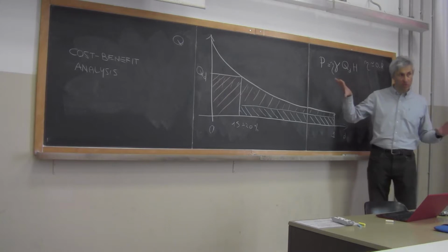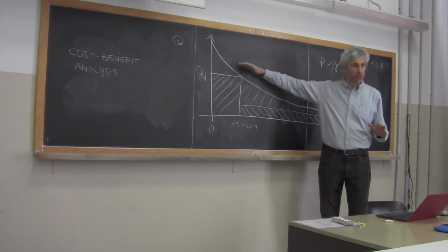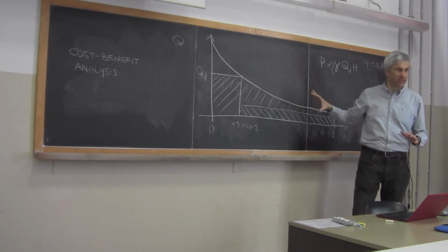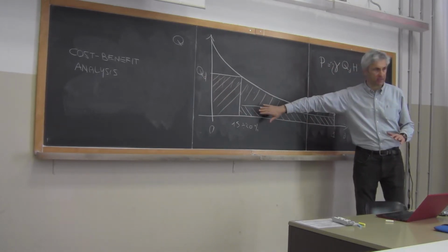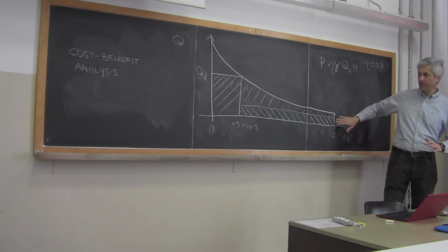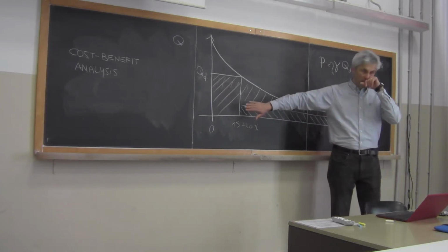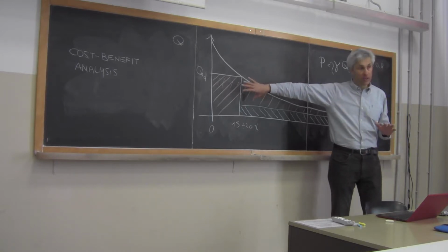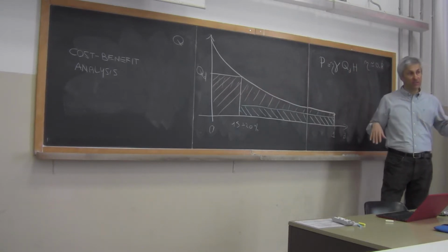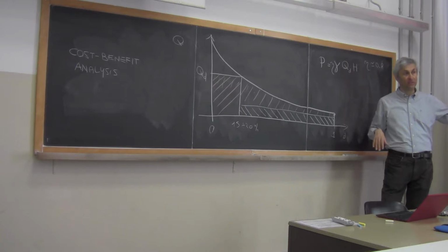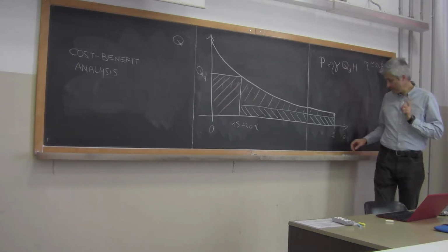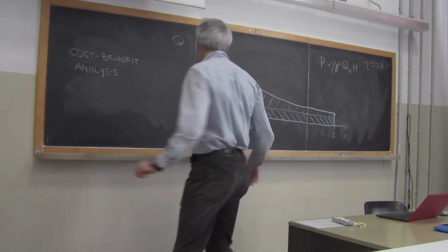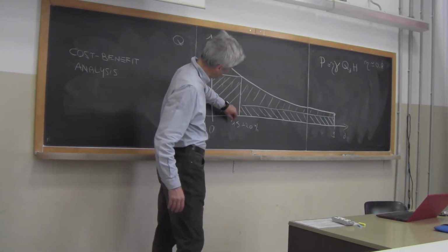Is this clear? So the area below the flow duration curve and below the design flow is the volume that I can potentially take. If I subtract the volume of the environmental flow up to the duration of the design flow, the area in orange remains the part that I can effectively, the volume that I can effectively take. But there is a critical zone here.